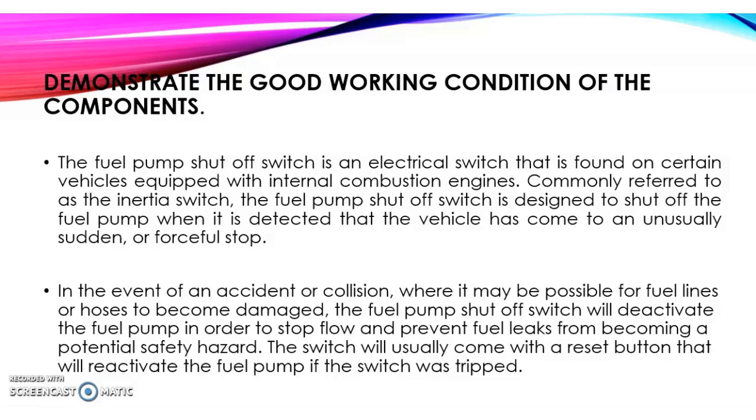Other than that, in an accident or collision, it may be possible for fuel lines or hoses to become damaged. Then the fuel pump shut off switch will deactivate the fuel pump in order to stop fuel flow and prevent a fuel line from becoming a potential safety hazard.